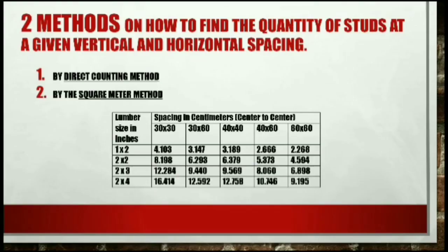So there are 2 methods on how to find the quantity of studs at a given vertical and horizontal spacing. It is by the direct counting method and by the square meter method. Later I will show you how to use those methods. Here you can see a table which shows the lumber size in inches and spacing in centimeters and its corresponding multipliers. Later we will also use this in quantifying the studs.